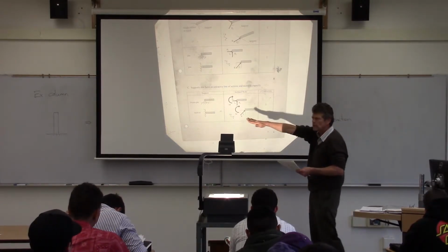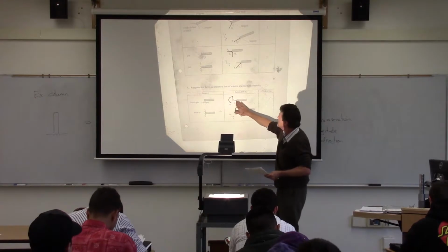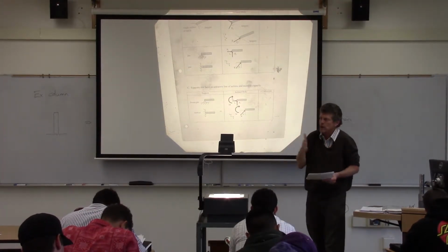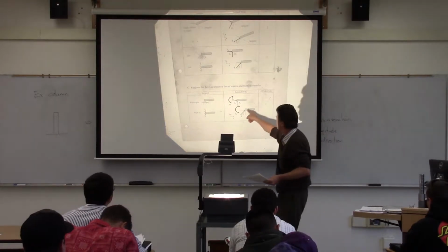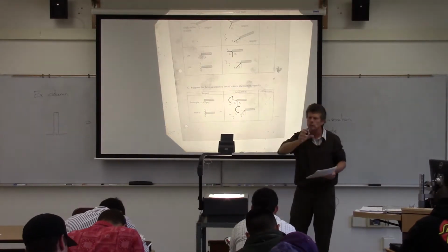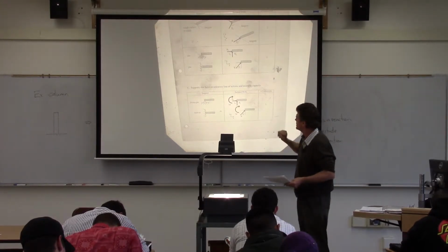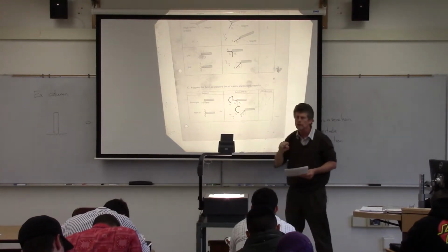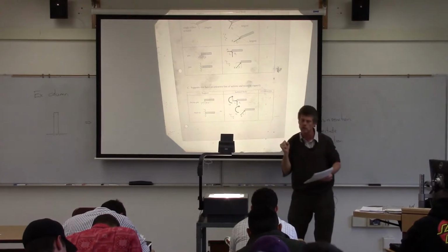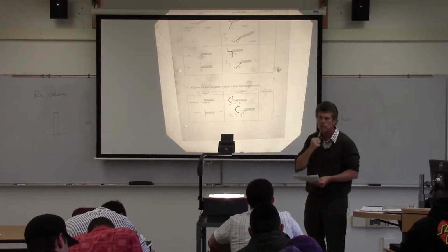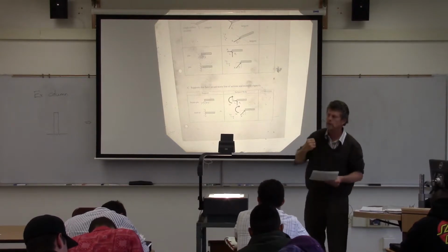And this is where we're going to have our cantilever beams and that sort of thing. So what we're going to do is substitute in what we had with the pin before, those x and y, z components. So it's an unknown force, but also there's a restriction in terms of moment. It's not going to allow it to rotate. So if I try to rotate that frozen pin, the built-in condition is going to say, not only am I not going to allow you to go in the x direction or the y direction, but I'm not going to allow you to rotate either.